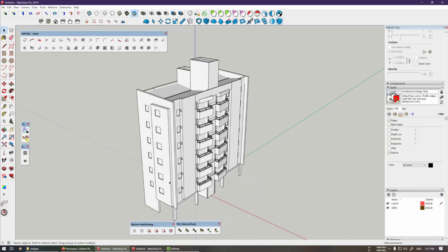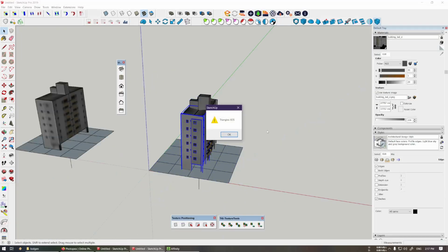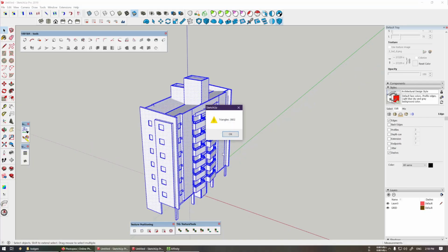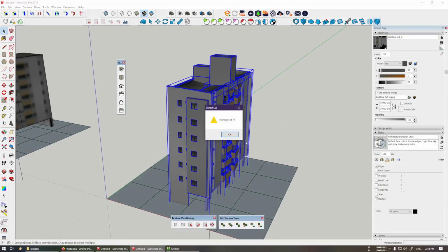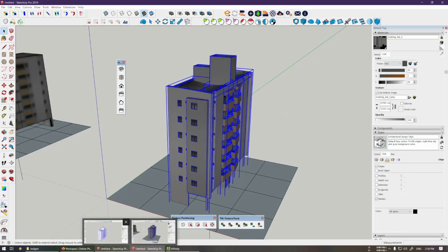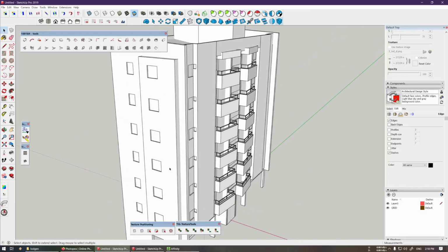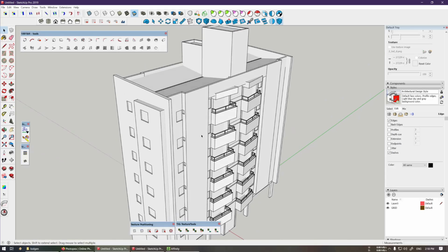Explode everything. Now you check how many triangles your main model has. 3500. After explode, how much? 3800. There are some areas that merge together, but a few hundred is fine. It's not a big deal. But if you went from 3500 to like 4500 or 5000, then you've got a problem to fix. Something is merging, causing an excessive amount of geometry to be generated.